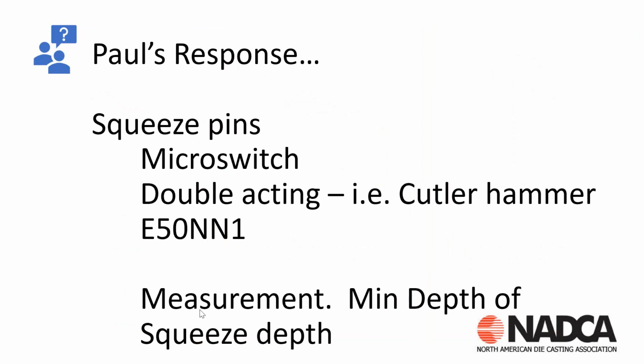And the other way to do it is to physically measure the minimum depth of the squeeze pins. So we want to make sure that we're past our minimum, but we haven't gone to a maximum depth. Once again, otherwise it's just acting like a core pin.